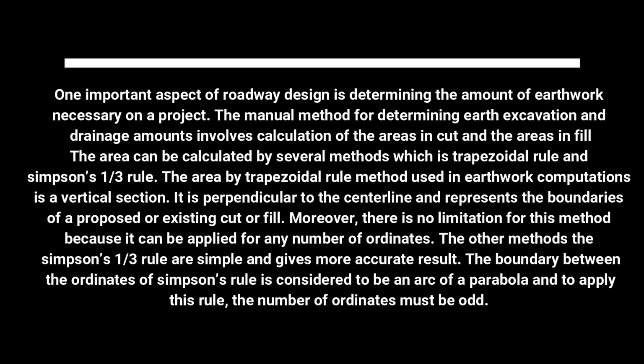The area by the trapezoidal rule method used in earthwork is a vertical section. It is perpendicular to the center line and represents the boundaries of existing cut and fill. Moreover, there is no limitation for this method because it can be applied for any number of ordinates.